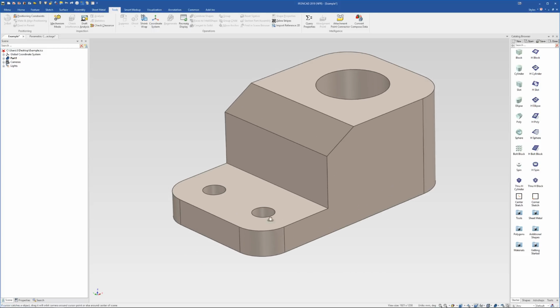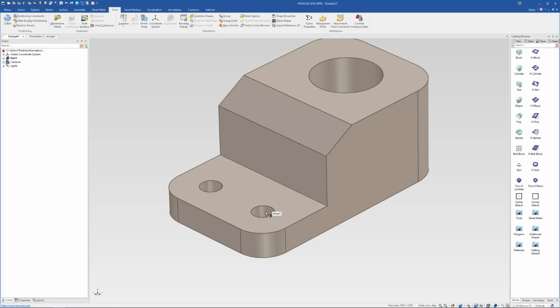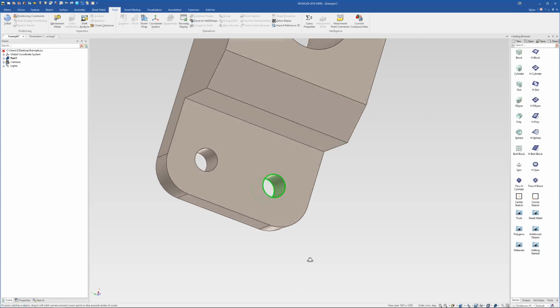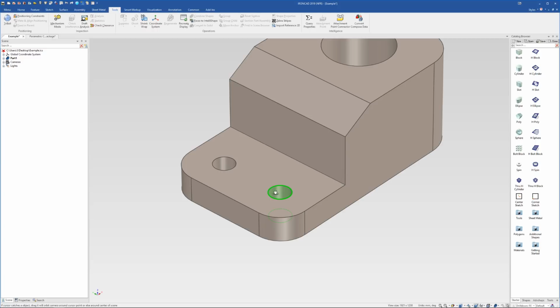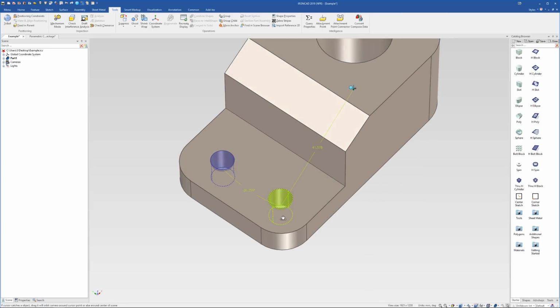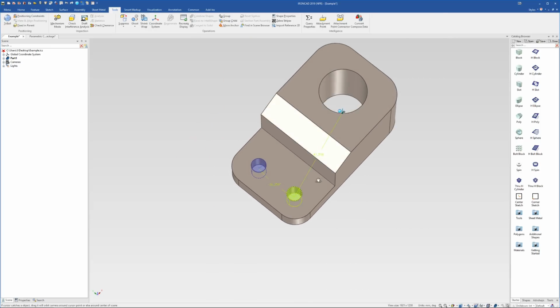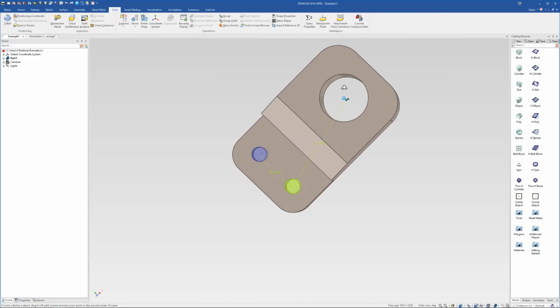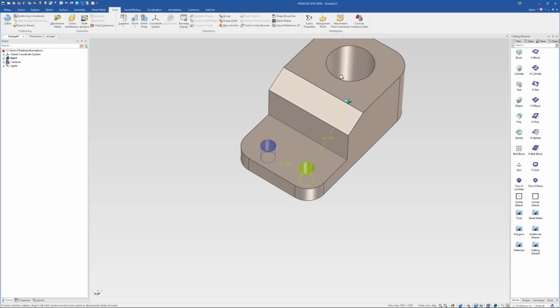One last thing for editing imported geometry like this is that you can select down and create IntelliShapes. So if we select down to a shape like this, where we're selecting all the faces that encompass that shape, we can then right click and do faces to IntelliShape. This is going to convert them over to a different face and then create a pattern from whatever it thinks is the best option for that pattern. You can see it's actually created a pattern via the midpoint of this shape and created those two in that pattern. So these will always stay the same and stay matched.